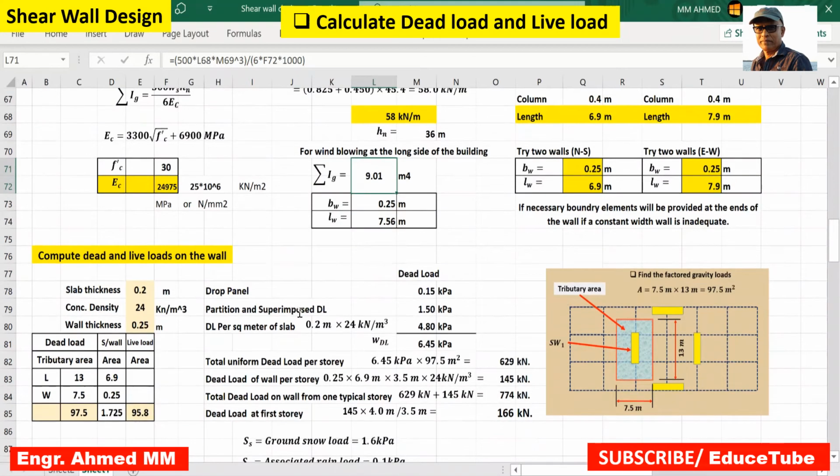Now we need to compute the dead and live loads on this wall 0.25 by 6.9. So here I calculated the shear wall area 1.725, because tributary area 7.5 by 13. How it comes?